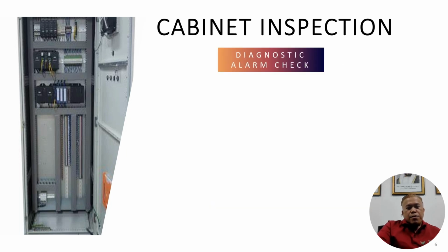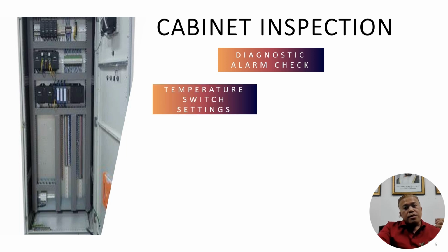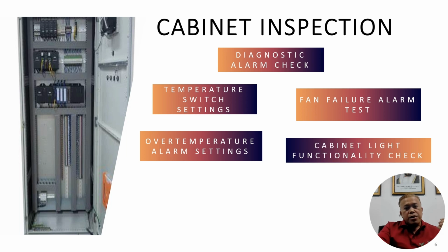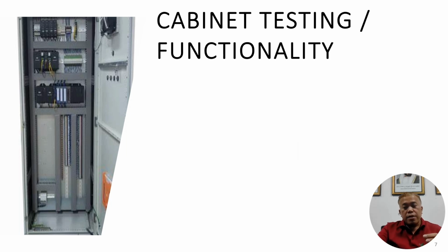So for cabinet inspections, you have a diagnostic alarm check, temperature setting, fan failure, over temperature, cabinet light functionality check, because every panel we have a fan, we have a heater, okay?